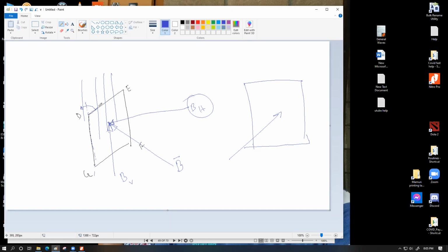then this D part will definitely cut across those vertical magnetic field lines at a 90-degree angle, and this FG part will also cut across those field lines at a 90-degree angle. So let's say this is the possible new position of the window after 90-degree rotation. So DE and GF, they will produce exactly equal EMF because they are of equal length.